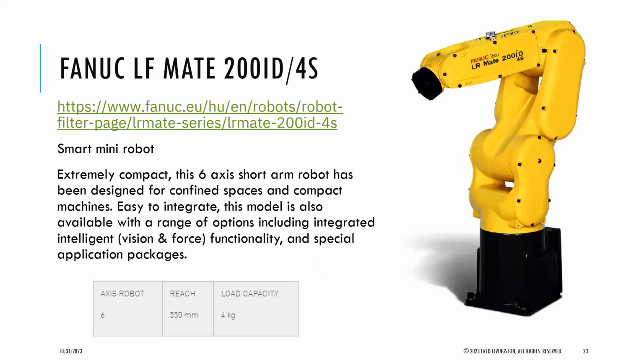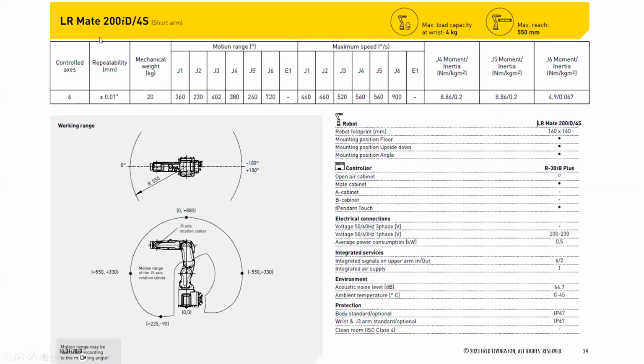And here is another popular one. You may have seen this one here. This is the Fanuc. And I've worked out the DH table for it. This also has some joint limits here. So the first joint could go 360 degrees. I mean, it could move all the way around, but that is the base. The other joint only has 230-degree motion here.